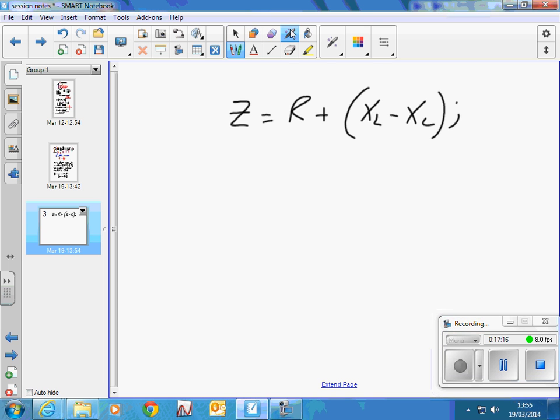This is the total resistive effect of the circuit, which is a combination of the real resistance and the reactance of the system due to the charges oscillating. So this effect comes into play when we've got an AC circuit, not when we've got a DC circuit. So we're talking about charges oscillating backwards and forwards around this circuit. There's not a lot we can do about the resistance of the circuit. That's due to the physical properties, the pure resistance of the circuit. What we can affect, though, with the frequency, as we've talked about already, is the reactance of the capacitor and the inductor.